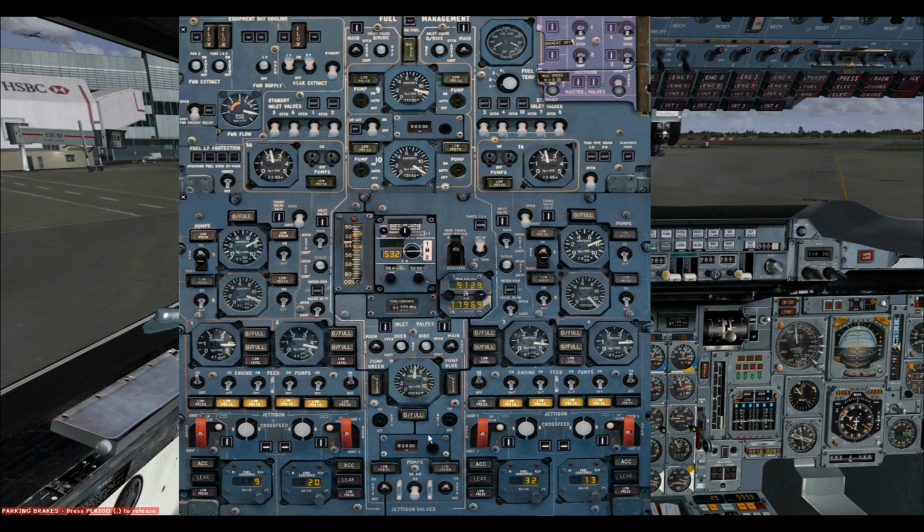If you're using the Concorde performance system, it'll actually give you a value to put into your load limit controller. I'm thinking that today the limit is going to be something like 7,000, maybe a little less, but we'll just throw it up to 7,000 for now, and we'll move our fuel back. I'm just going to watch it closely and go through this step by step. So let's slow down here.